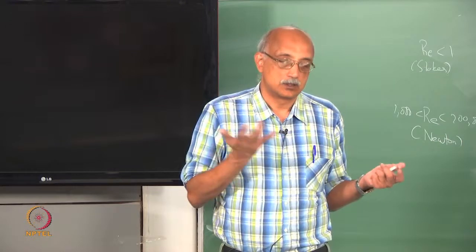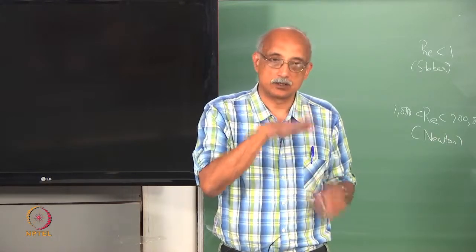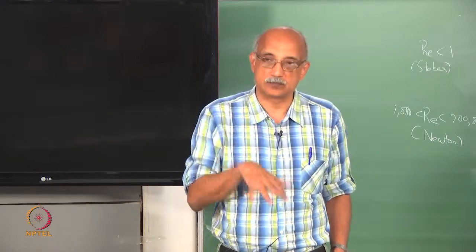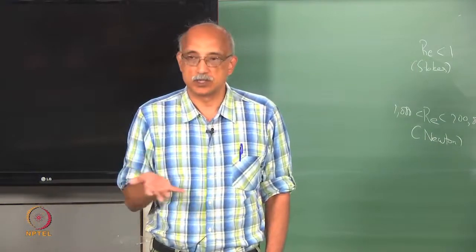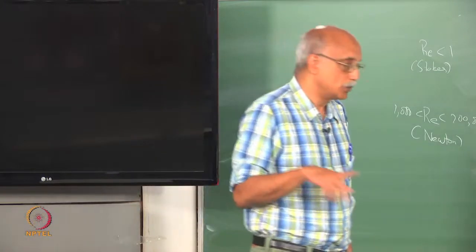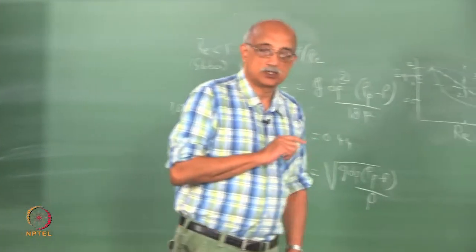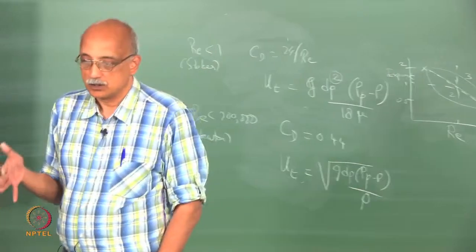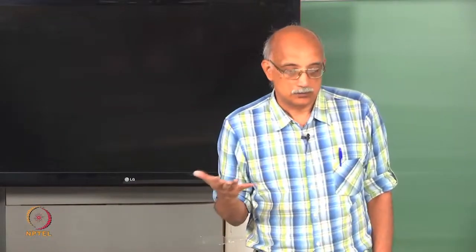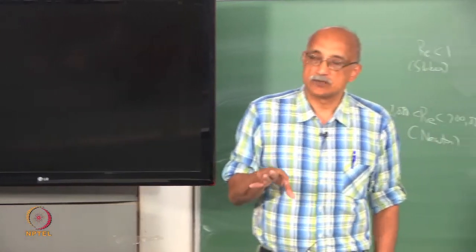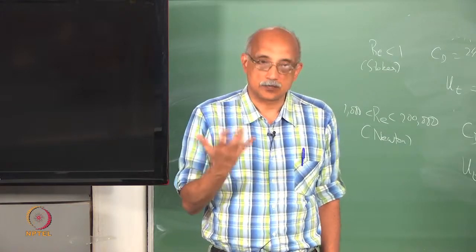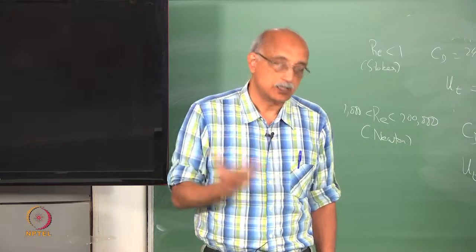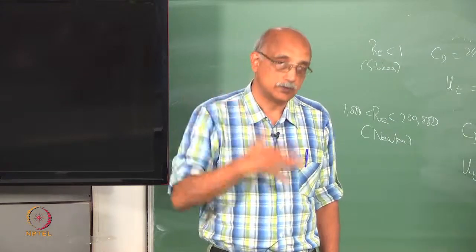You have particles that are fixed and fluid moving past them initially. Over time the particles themselves begin to move in the fluid. In terms of the flow regime, you are going to be transitioning from a regime which is laminar or low Reynolds number to begin with, to a situation where the flow velocities are sufficient that the particles comprising the bed actually begin to get entrained and move with the flow.